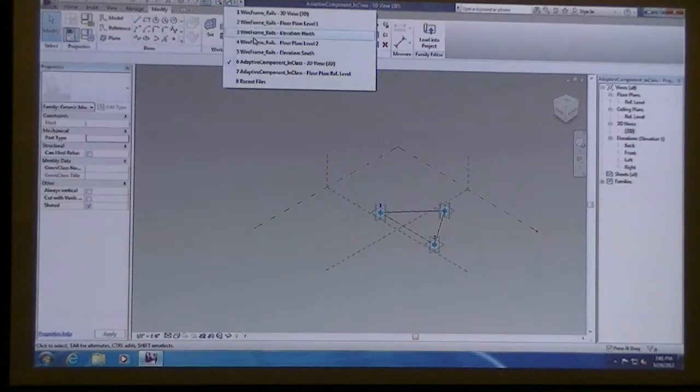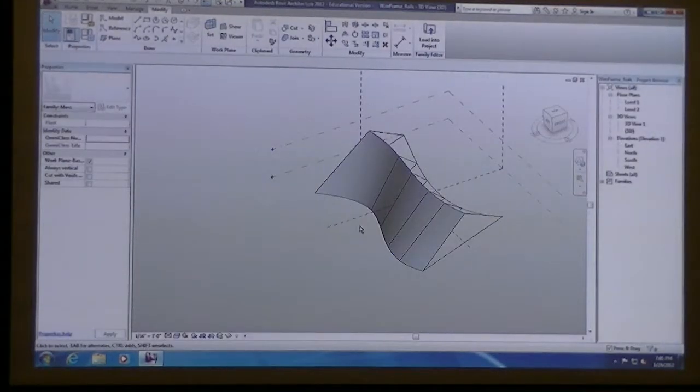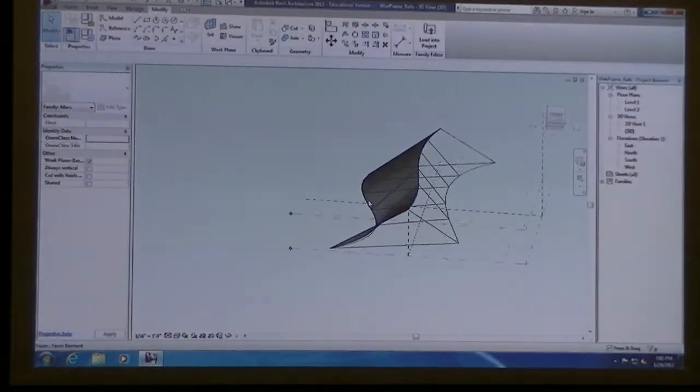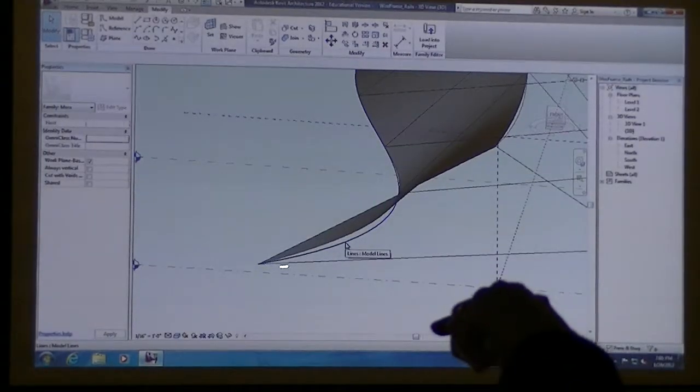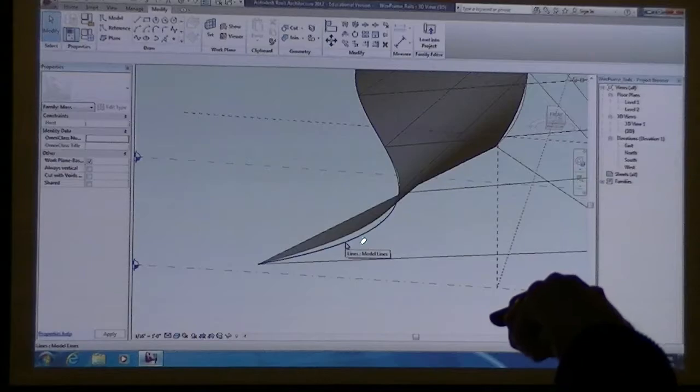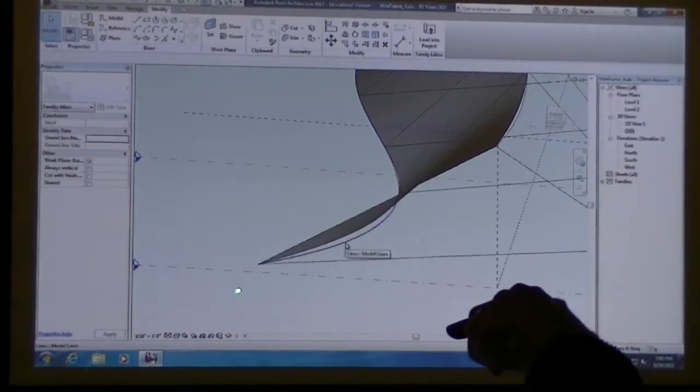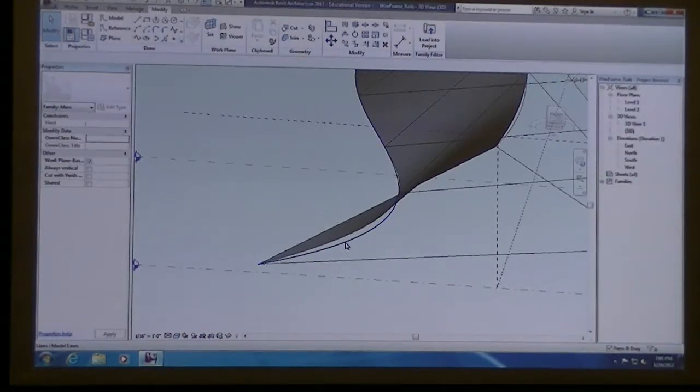So that doesn't follow the splines. Oh yeah, it doesn't follow. So what happens there? You probably notice the surface doesn't follow this line. If you look at my lofted surface at the top here, you see how it doesn't follow that bottom rail? That's because you're actually lofting the section curves along that rail.